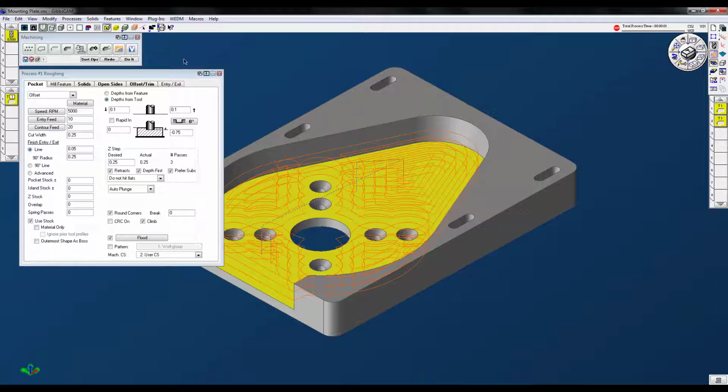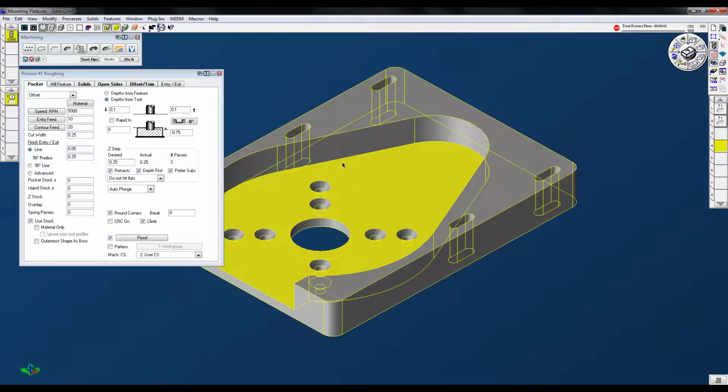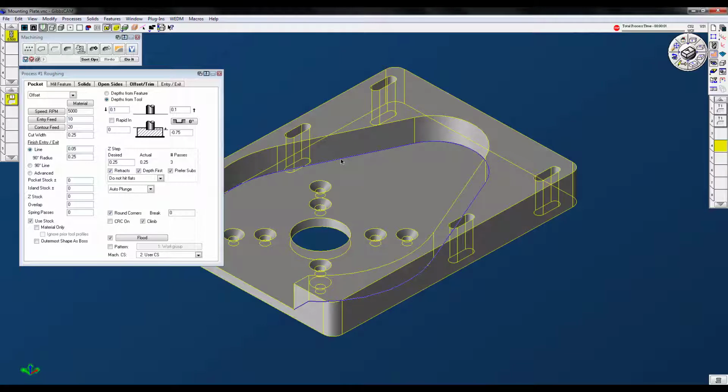I'm going to use the wireframe. So remember, in the very beginning, what I did was I selected that wireframe and set extract features. So I'm going to do edge select. I'm just going to double click on that edge, select the edge all the way around, right mouse button click, and say extract edges. Do it. There we go.